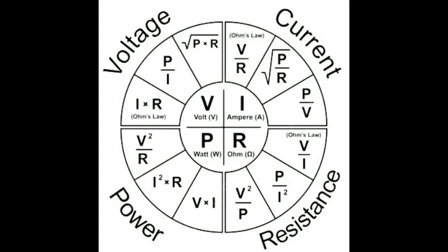Any other questions? Is this when you build a new electrical system? Let's say I'm building a house, and I need to install electricity? You have to understand what happens to amperage if you're wiring it in parallel. Now remember, all of our circuits are wired in parallel in a house. So I have a circuit that has 20 amps, right? The circuit is 20 amps. The wire is rated for 20 amps. That's the max of amperage that can flow through that wire.